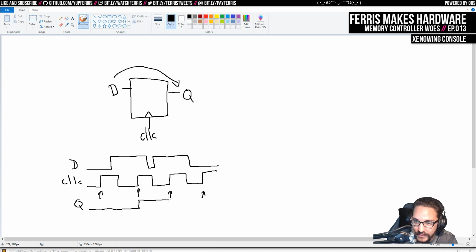And we're going to keep going until this edge, and it would still be high, so we actually missed this low pulse, which could be a glitch, it could be anything. And then that's going to continue until this one, where it would be low. And this is really fundamental for making logic circuits that actually work, is this kind of synchronized sampling of the inputs.